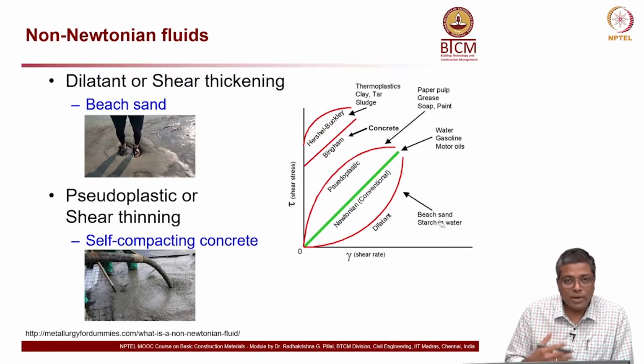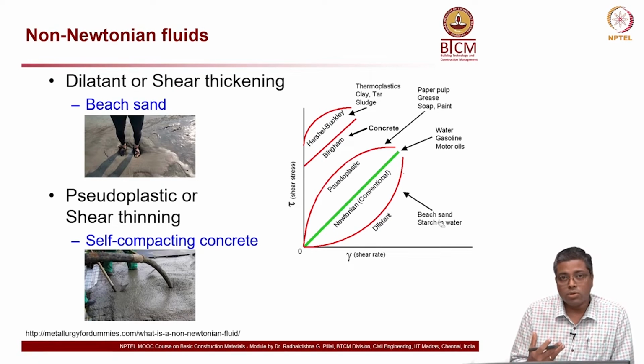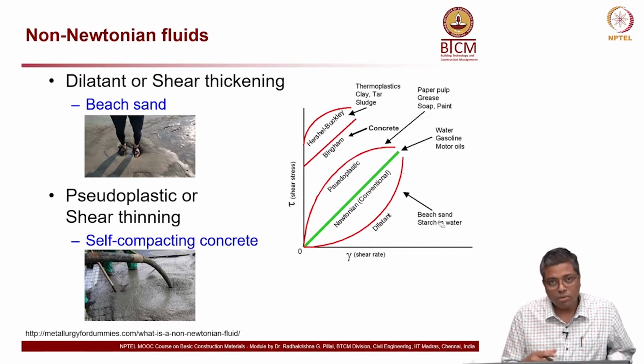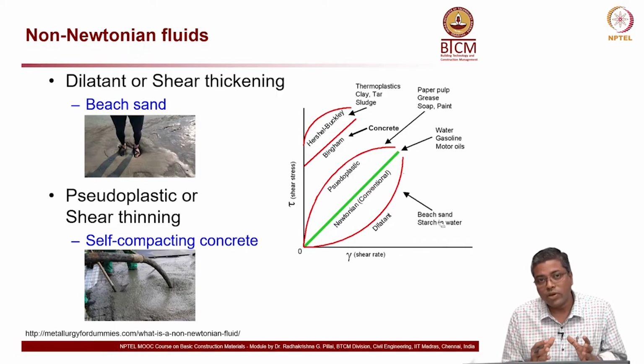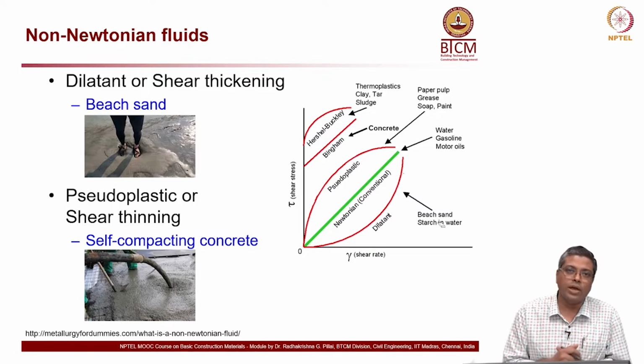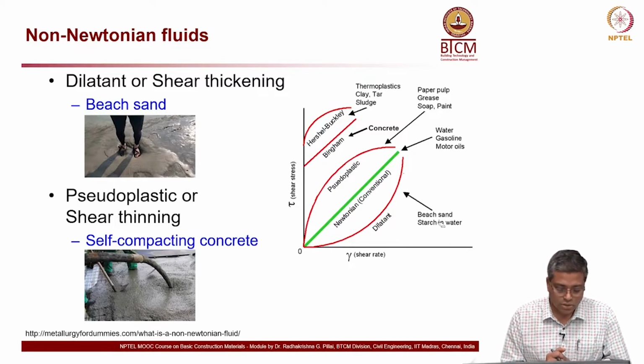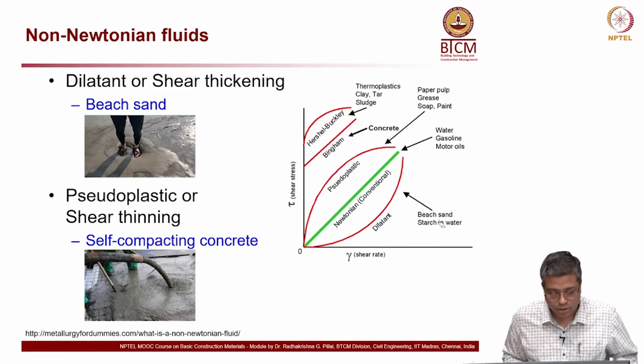For application purposes, self-compacting concrete is very good, because the amount of energy required to mix or place the concrete is less. Once it starts moving, it will flow by itself, maybe very slowly, but it will flow and then fill all the small spaces, nooks and corners in the formwork, etc. It will fill up very nicely. The use of this material is increasing day by day, so you will hear about this more later.